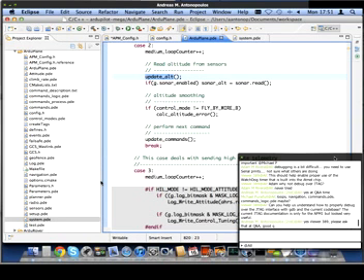On the APM2, however, it's an SPI device, and we can currently support interrupt-driven drivers on the ArduPlane code and ArduCopter on the SPI bus, and so the barometer on the APM2 is called at 1 kilohertz. It then downsamples that to 100 hertz, and it internally averages between the times when you call update out.